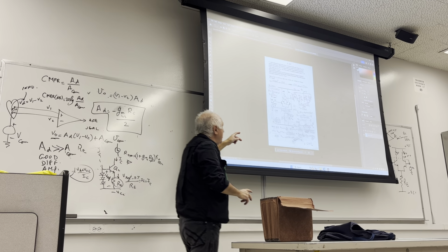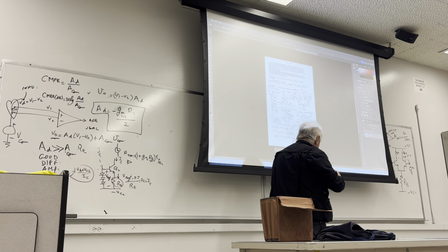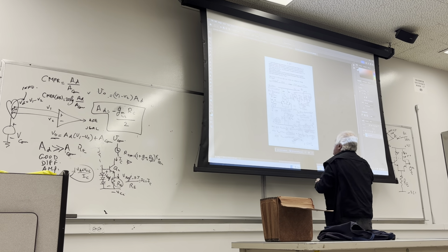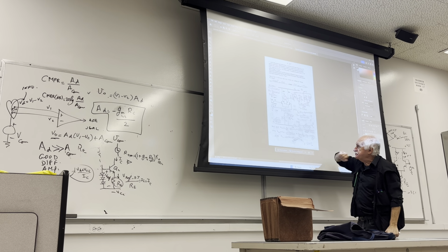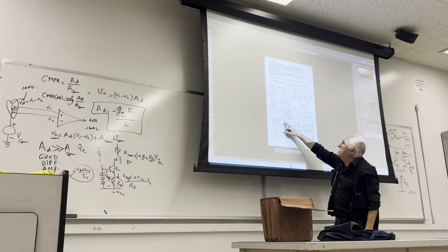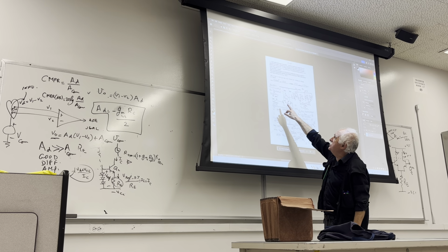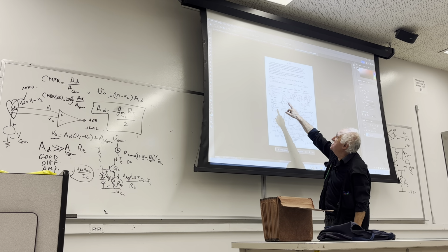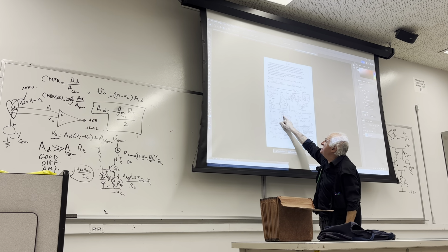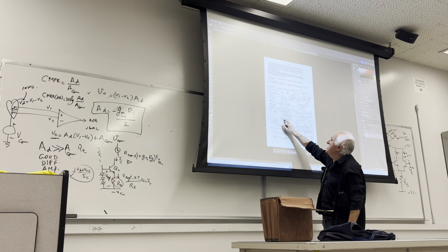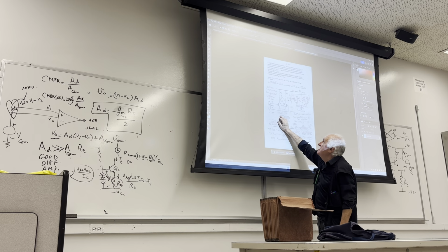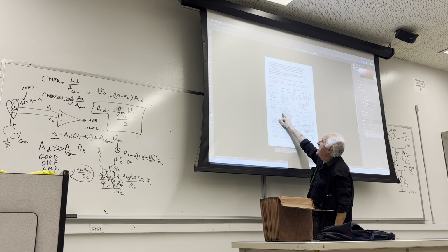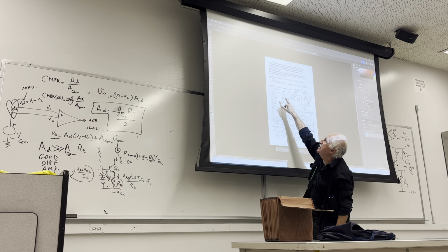So let's see what is here. So remember how to calculate: our rπ is 7.1, GM is 21 millisiemens, IC is half of the IE current in here. So if this is 1 milliamp and that is about 0.1 of a milliamp, 1.1 milliamp, each transistor is holding half of the 1.1, 0.55 milliamp.